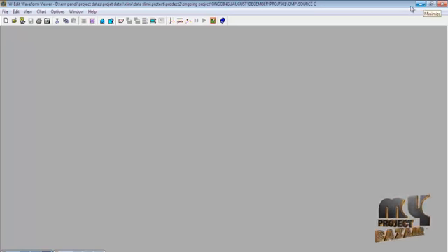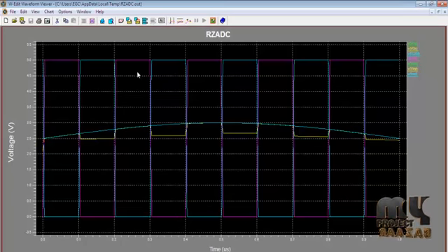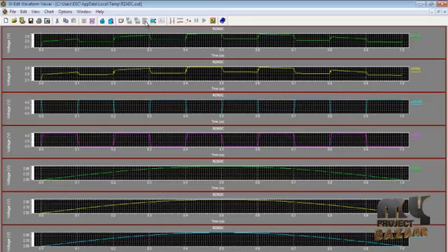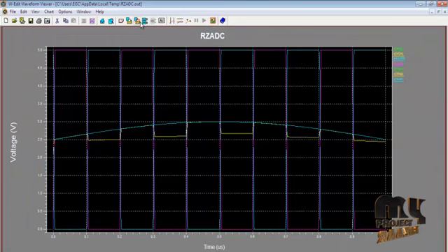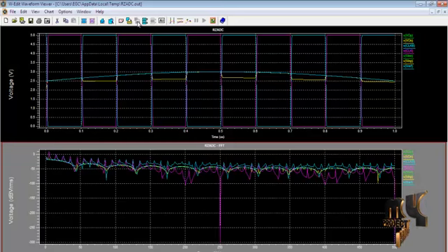In the WEdit window, first one, the input and output data of the corresponding output, and this is the normal overall output. Then we click the expand chart, then the output will be separated in that format. So this is the corresponding output waveform. And next, if you want to see the frequency value and also the FFT analysis for that corresponding output, we click the FFT, then the output will be displayed in the frequency as well as the dB ranges. So this is the overall input and output waveforms.